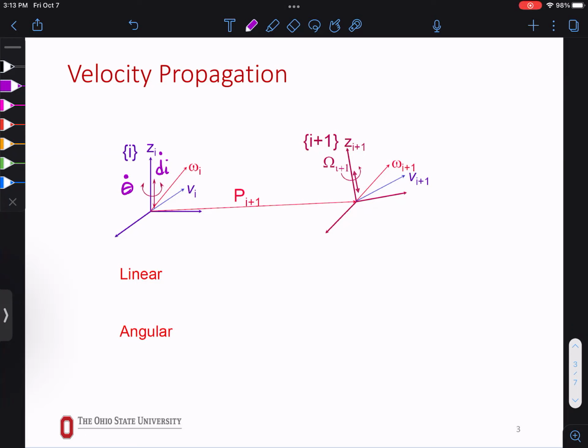All right. So for the linear velocity of joint vi plus 1, for the next joint, for this joint, what component can there be for the linear velocity for this setup, knowing that we don't know what this previous joint is? It could be a prismatic, it could be an angular. So what component would you expect to see in the linear velocity of that joint i plus 1?